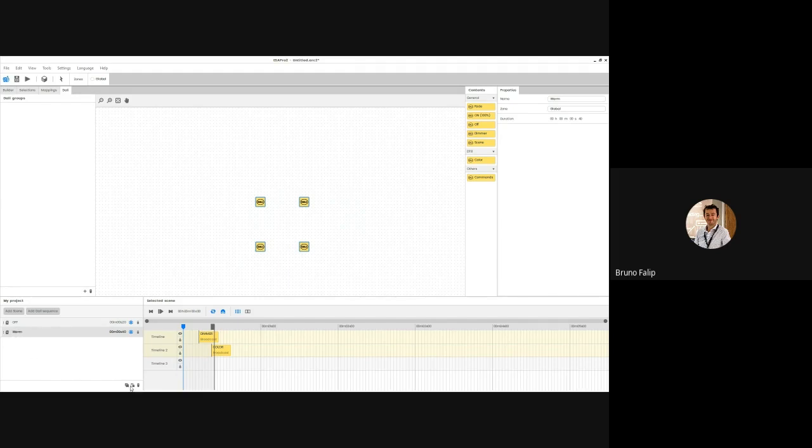So you can copy paste the scene. Oh, sorry. Copy and paste. Okay, so 1, 2. Let's call it warm 75%, for example. I just have to edit the dimmer. Remember, DALI command, and you can put 75 here. Okay, and I've reduced to 75%.